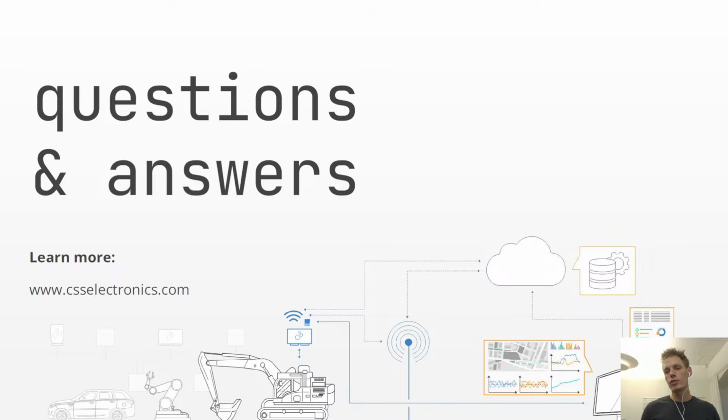But the device does not support seed and key authentication, which is essentially a bit like exchanging a password with the ECUs on the CAN bus. So for that purpose, you will need, for example, a Vector data logger or something similar. It is not something we support today. But if you're interested in this topic, we of course have an intro to CCP and XCP, and you will find it in our guide section.